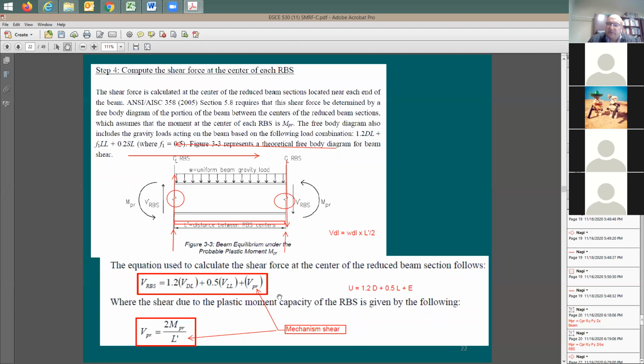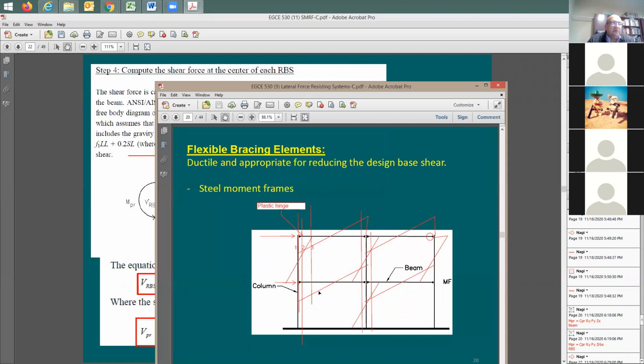It's going to be based on the actual performance of the building. Once you start to push the building with some displacement, this is going to be the amount of shear that you're going to be able to develop in the beam. So it is not related at all to the moment and the shear distribution that you get from the given seismic forces. Does this make sense or no? I'm not clear yet. Yeah, that makes sense.